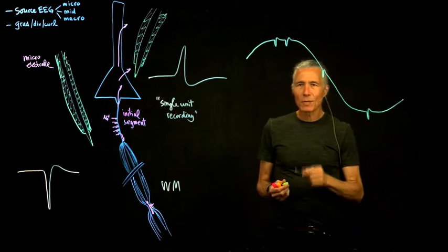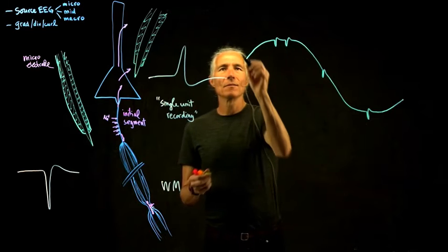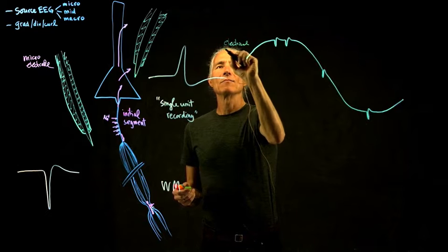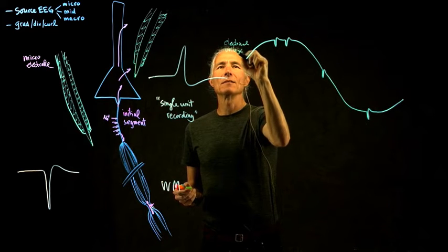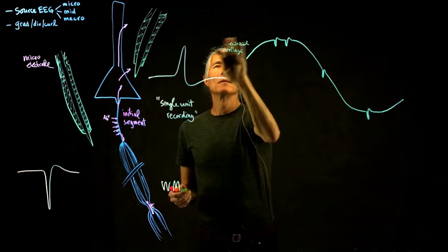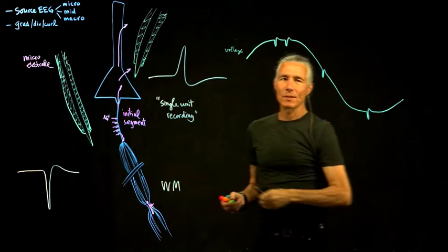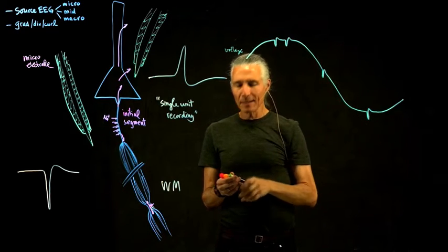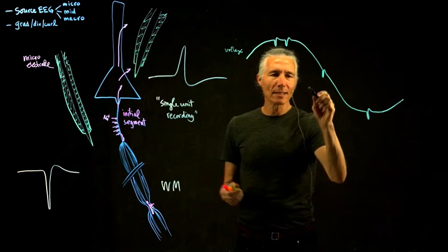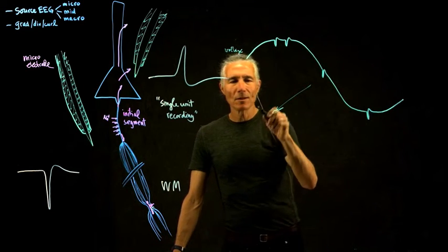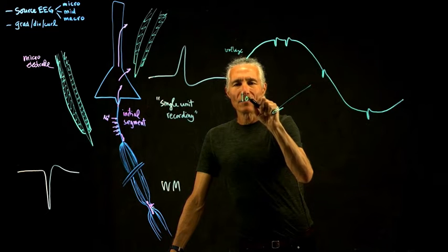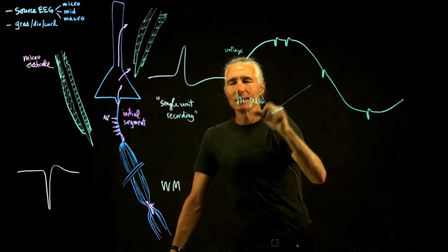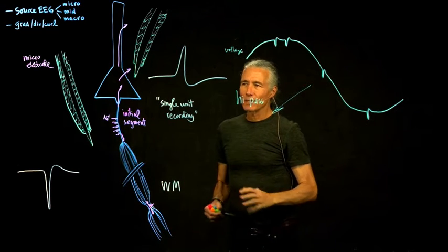So that's the actual electrical signal. This is the electrical voltage coming out of the electrode. So it's got two things in it. It has these very rapid spikes, and when you take something like this, what you can do is a low-pass filter. Well, let's do a high-pass first. A high-pass just means just let the high frequencies through.